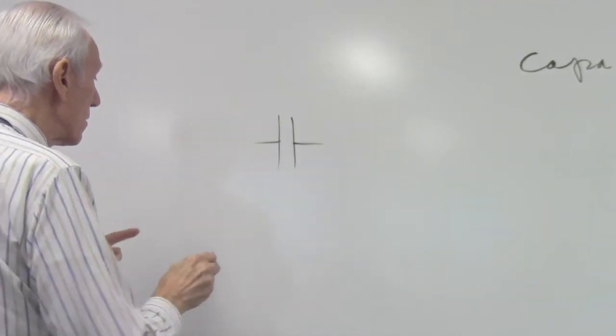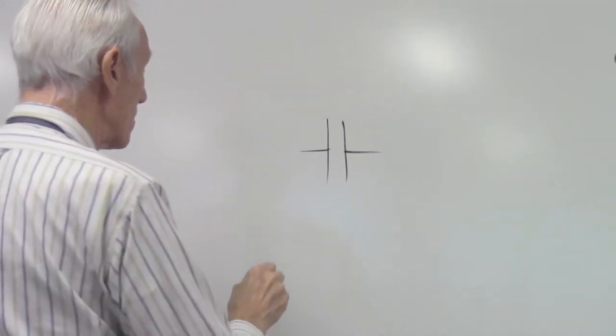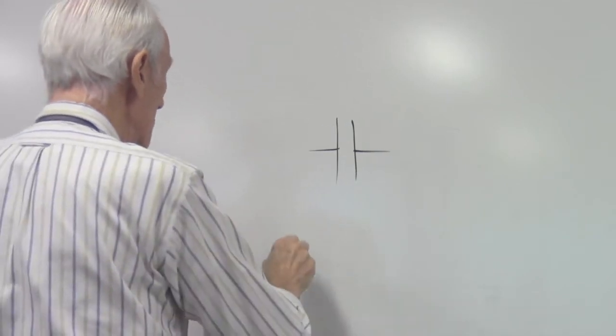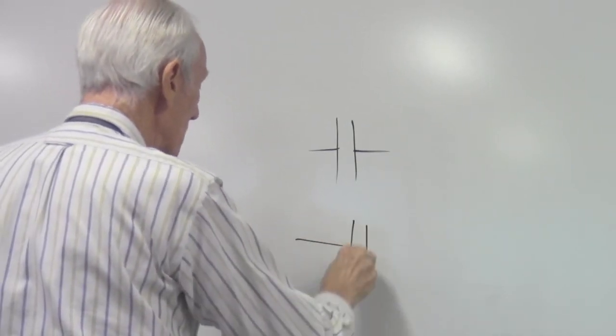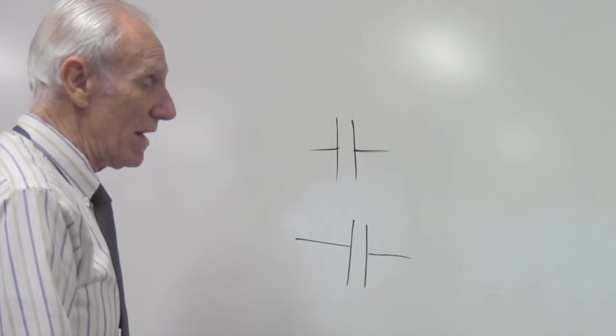Our capacitors are a little bit different. They're electrolytic capacitors. They have an electrolyte in them, and that electrolyte can be destroyed by hooking them up backwards, so please don't do that.